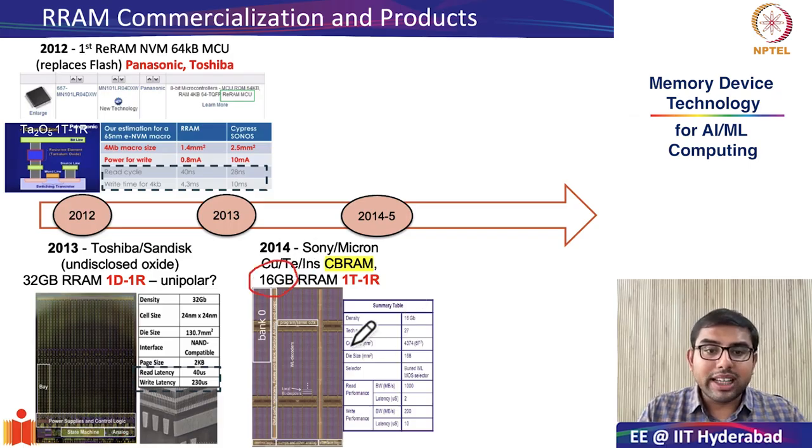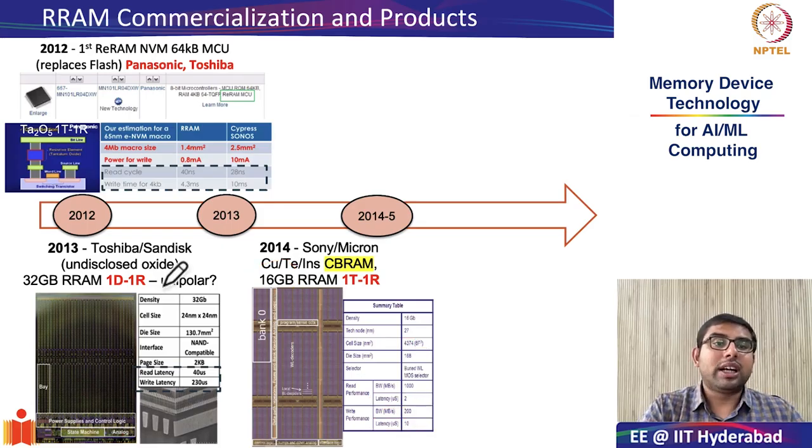What was very interesting is that this particular RRAM array was able to achieve an area scalability of 6F², and this was done at the 27 nanometer node. Also, what was significant is that the read latency and write latency of 2 and 10 microseconds was a significant improvement from the previous demonstrations of large scale integration of RRAMs.